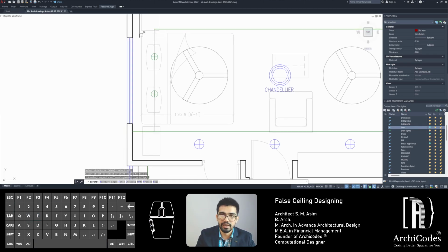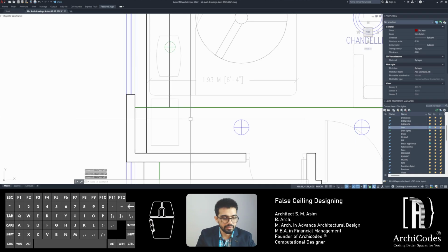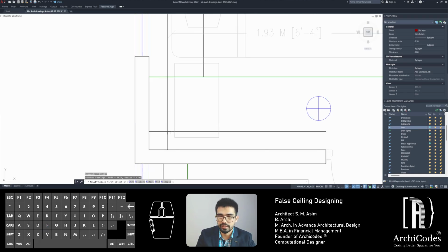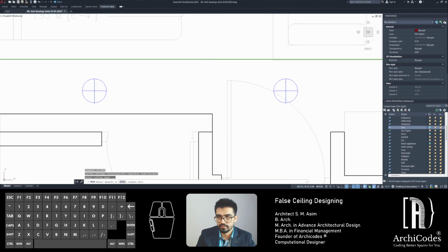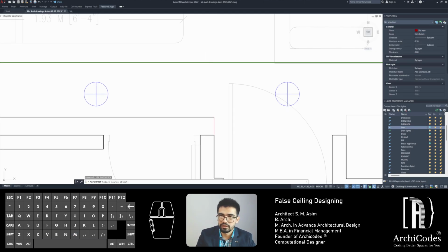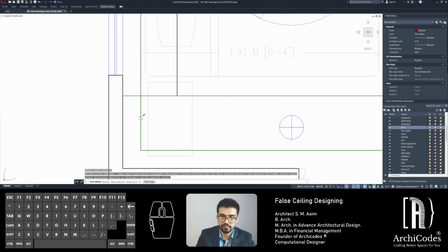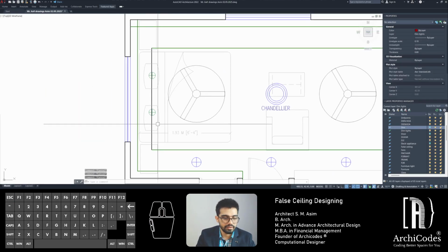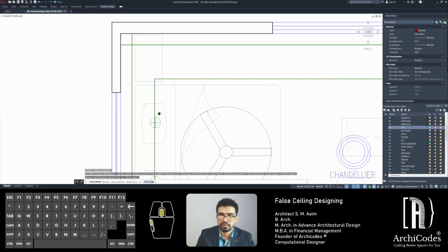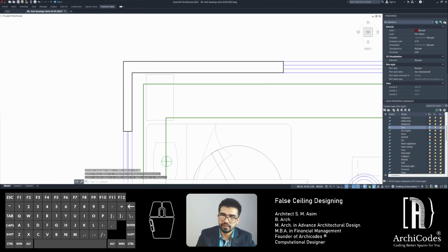6 inches because this is the bed back. We want to do something over there, we can. Again, offset 0.15 to maintain the uniformity, and this thing will go till here. Just wanna trim it, make a new line because it will follow the green layer, false ceiling layer. This thing ends here. Match properties. I need to fix the bed position, I think.